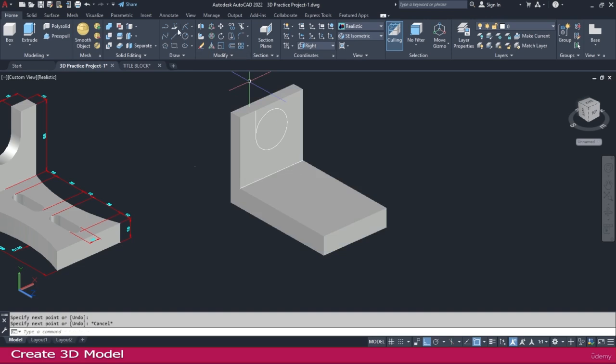I cancel, go to the line tool, click this quadrant and click here, escape. Now go to the trim tool, click this circle, and you can trim like this. If you made this circle and line in the exact same plane, you can definitely trim. Otherwise, if you struggle to trim, the lines and circle were definitely not made in the exact same plane.